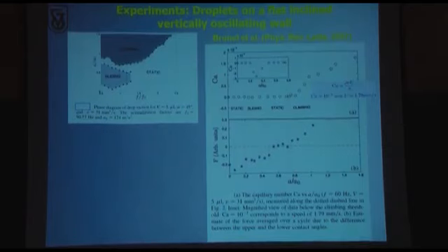By the way, if u is positive, the capillary number is positive. If u is 0, the capillary number is 0. If u is negative, the capillary number is negative. And just for scaling, a capillary number of 1 over 1,000 means u is about 1.8 millimeters per second. So it's a sizable velocity. It's not supersonic, but it's sufficiently discernible.